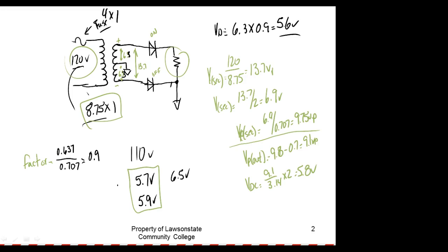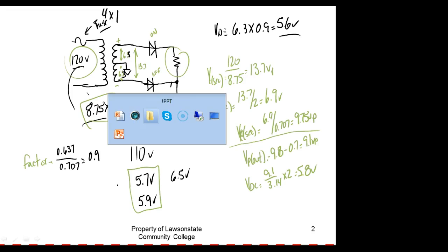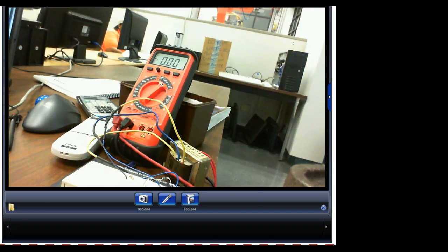No. It's usually going to be greater than that. This is a 1 amp transformer, so what that means, and we're getting 90 milliamps out of it, or I'm sorry, 9 milliamps out of it, right? I'm sorry, we're getting 18 milliamps out of it because we doubled the voltage. And so we're not loading the transformer near its rated current. I'm just going to come up here and measure the output.